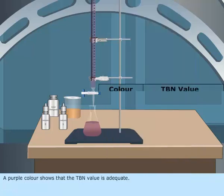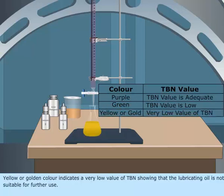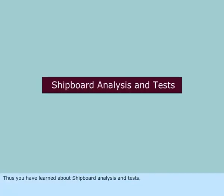A purple color shows that the TBN value is adequate. A green color will show that the TBN is in borderline. Yellow or golden color indicates a very low value of TBN, showing that the lubricating oil is not suitable for further use. Thus, you have learned about shipboard analysis and tests.